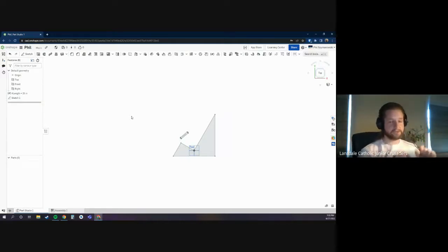It's really important to understand that sometimes sketches will be dependent upon each other. And if you make a sketch dependent on another sketch, that means that forever forward, that second sketch you made will always have to come after that first one. So just be aware of that. Most of the time, you won't have to reorder things. That's a pretty advanced technique. But do be aware that when you are reordering things, you have to consider what those things are referencing. All right, cool.